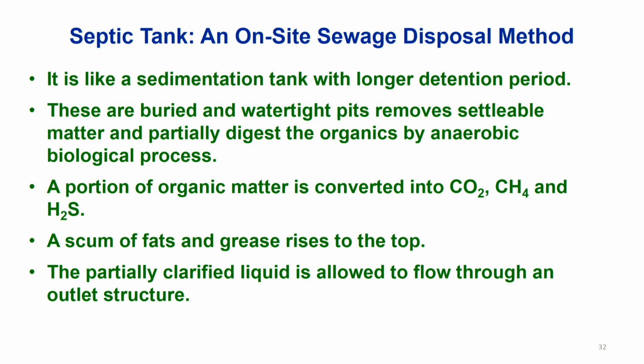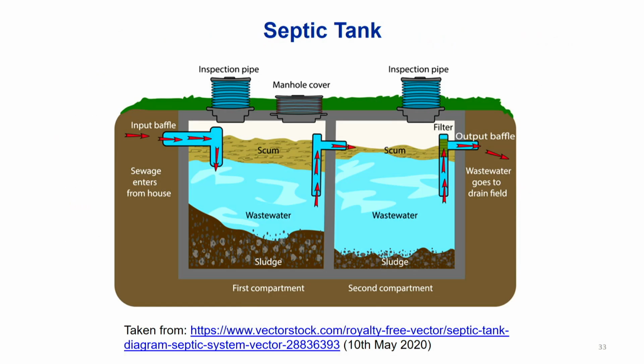A scum of this oily fraction rises to the top, and partially clarified liquid is allowed to flow through. So this is a schematic of one system where two partitions are there. An input baffle is provided so that the water goes in the downward direction and the lighter material rises up to the surface.